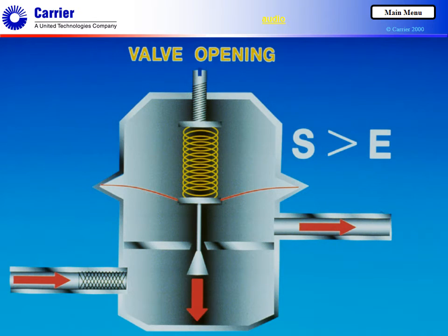As the evaporator pressure falls below 69 psig, the spring pressure exceeds the evaporator pressure. This bends the diaphragm downward and opens the needle valve. Flow to the evaporator increases, which causes more of the evaporator's surface to be flooded. If adequate cooling load is available, more gas is evaporated, and the evaporator pressure returns to 69 psig. Again, the spring and evaporator pressures are back in equilibrium.